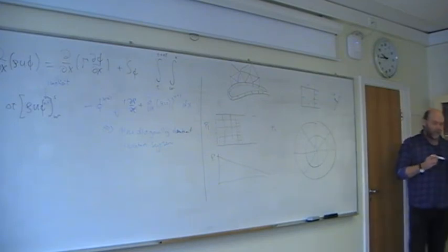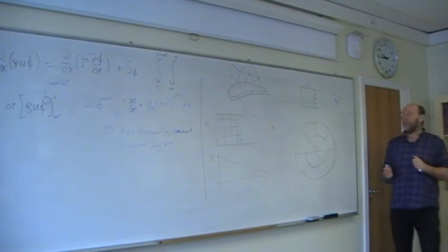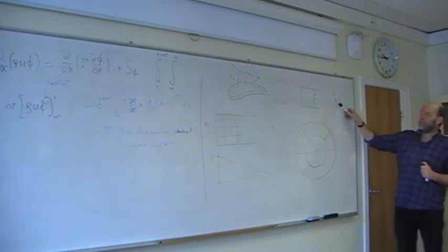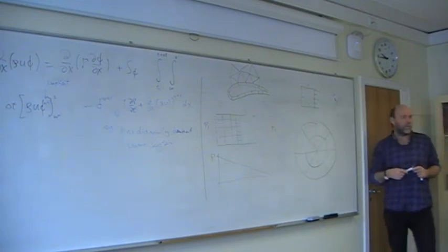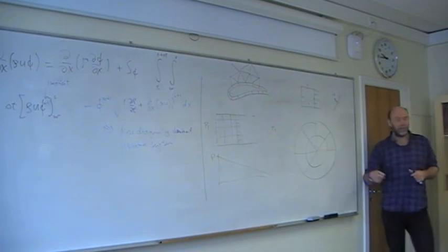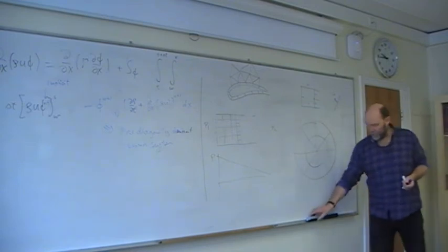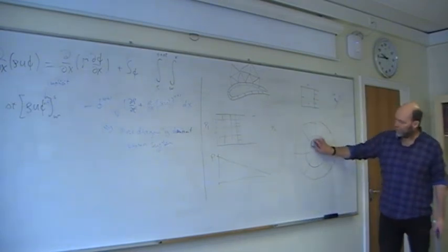Which is going to be very, very expensive if you think in terms of the Courant-Friedrichs-Lewy number. You should not pass more than one cell length during one time step. Okay, then you are asking for trouble. You can't do this. It's a very bad idea. So what do you do?